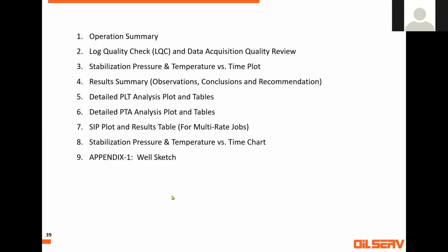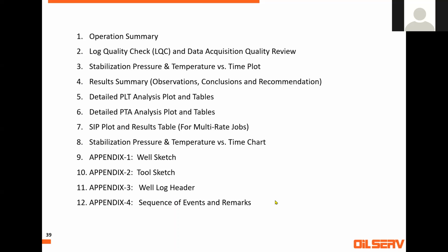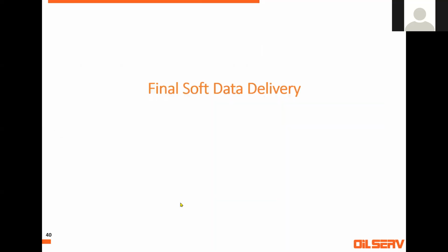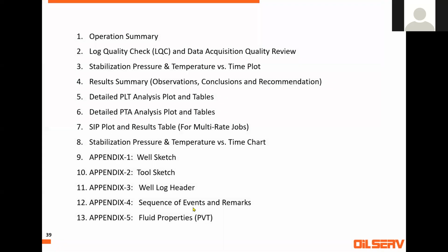You put the well sketch, you put the tool sketch, you put the well log header, sequence of events, and fluid properties, PVT that have been used in the analysis, in the PLT and PTA analysis. So this is the most common report sequence. Usually, if any of your students have worked for a company, there he will find some reporting format he will follow. Most probably it will be similar to this one, especially in a service company.